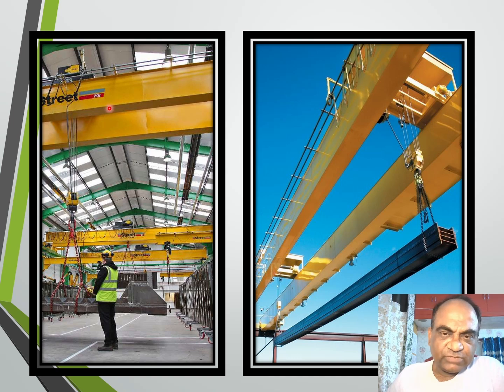So there is something called an anti-collision device, which is very necessary or essential in these cases, because these two cranes can collide with each other. In order to avoid any kind of collision that damages both the cranes, an anti-collision device is a kind of sensor put on both the cranes, so that if they come in proximity, an alarm will start ringing in the cabin of the operator, and that will alert him.